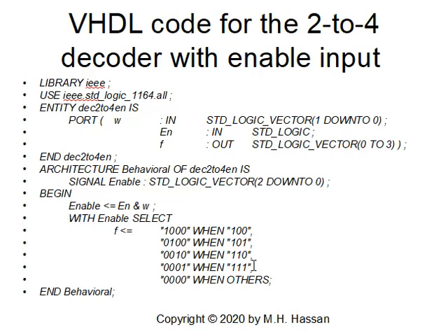So this is actually a better design for the decoder with an enable signal, because the output will be all inactive if the input comes in any form starting with 0, because the enable is then inactive.